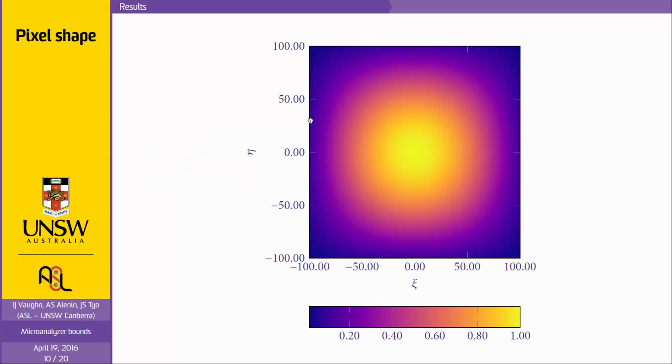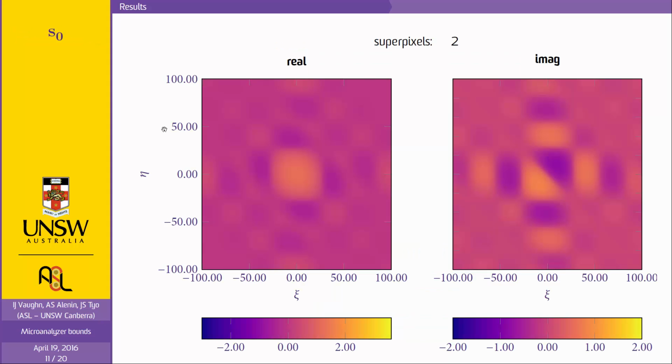I'm going to show some results using a conventional linear micropolarizer array. We take the Fourier transform of the pixel shape. Of course, we just get a sinc function. So here's the center lobe of the sinc. These axes are in frequency per millimeter, spatial frequency. And we've assumed a square pixel. It's 9 by 9 microns.